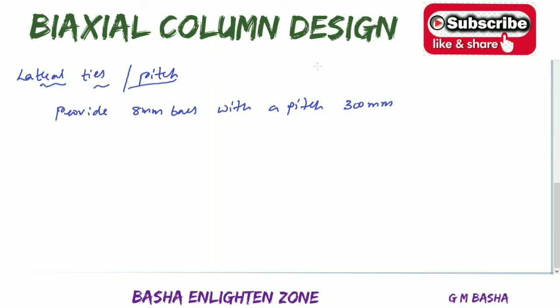Least lateral dimension will be equal to 400, that is 400 in our condition, and the second condition is 3 times the longitudinal bar diameter, that is 320, and the final condition will be 300. After solving so many problems, you can directly know what we have to provide. So provide 8 bars with a pitch of 300. Maybe there is a chance of getting 6 stirrups after solving this one. You can provide that also, no problem.